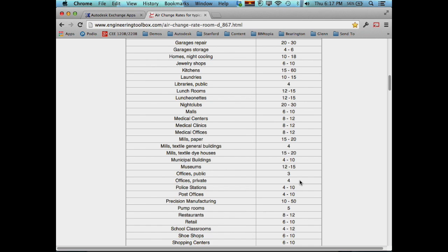Okay, so next time you're hanging around in a house, check out where all the radiators are. Check out where all the registers are. They almost always are near the doors and windows and stuff like that. Because even in a big space, let's say you have a big building, we'll use the strategy of introducing all the new air, or all the conditioned air, out near the windows.